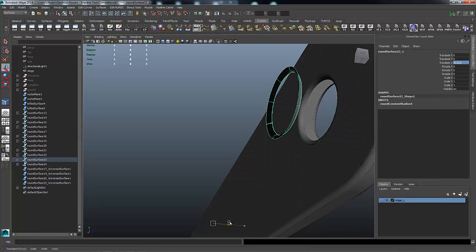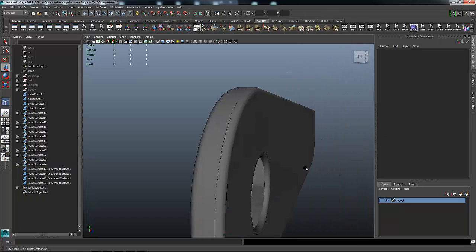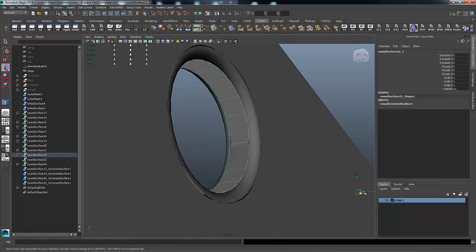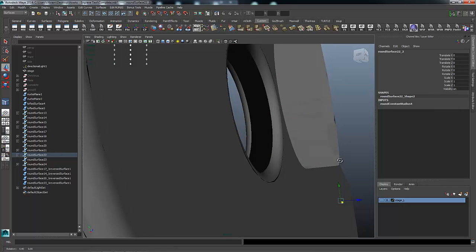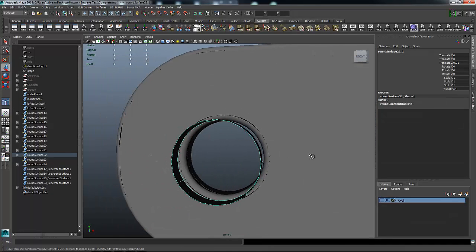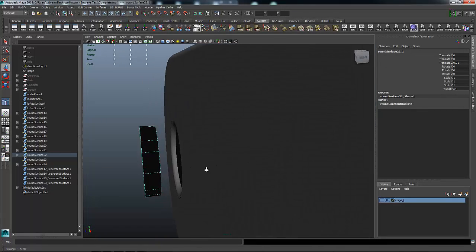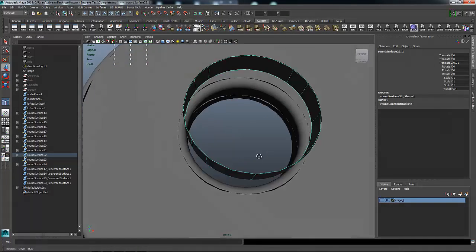Select that face, pull it out. That's the bad one, so we'll just delete it. And then I already deleted the ones on these edges here, and let's see if we also have that problem in the middle. And we don't. Although that's still kind of strange, because if you notice, this surface I just pulled out doesn't seem to have a... Oh, that's weird. It's reversed from this direction, but it's not reversed from that direction.